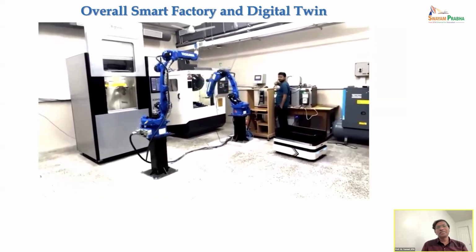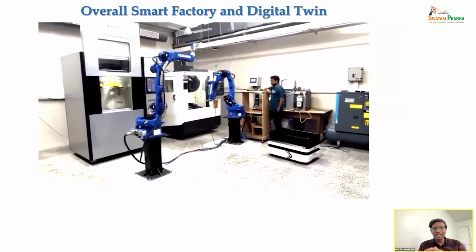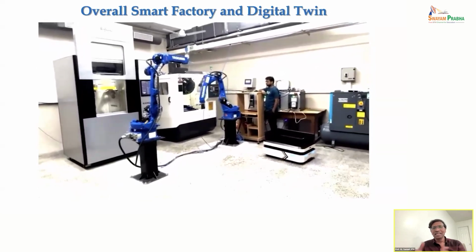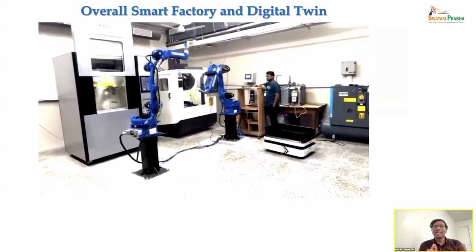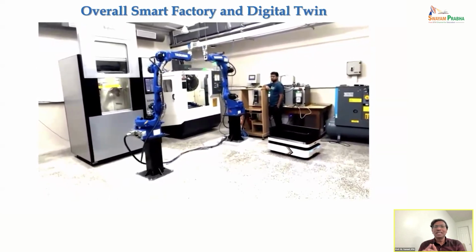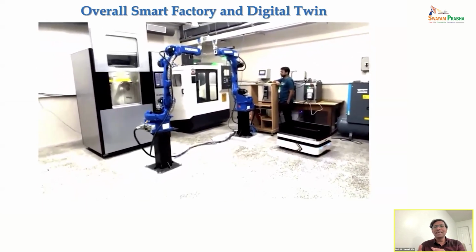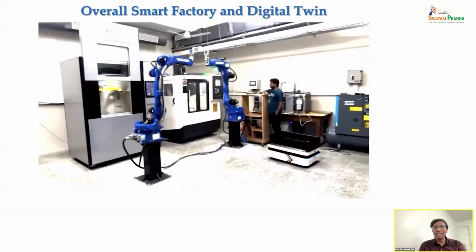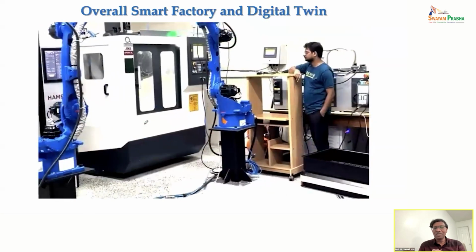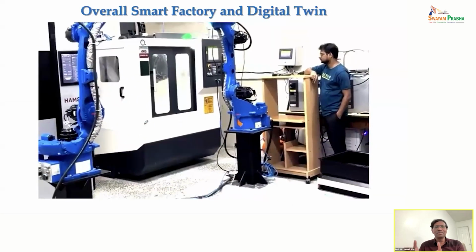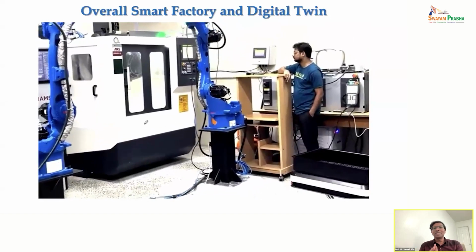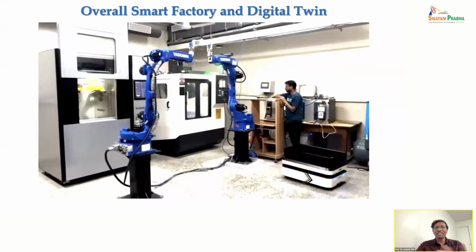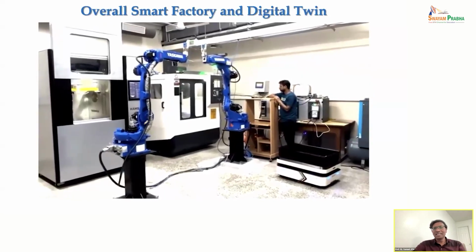Initially, when we had the 3D printed component and made the automatic clamping, the clamping pressure was so high that the workpiece was crushed. Later we had to put in sensors and tell them that only this much pressure can be applied, otherwise it can even crush the workpieces. Then the machining cycle starts.